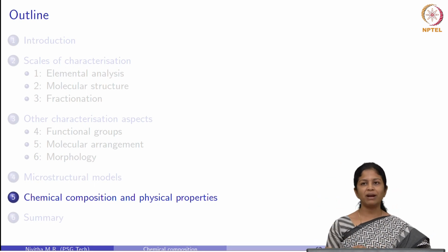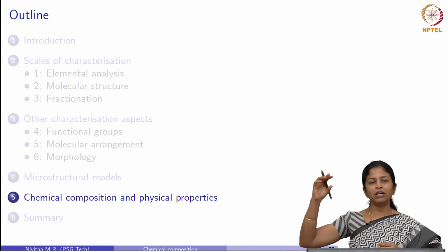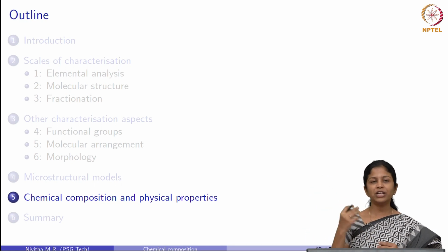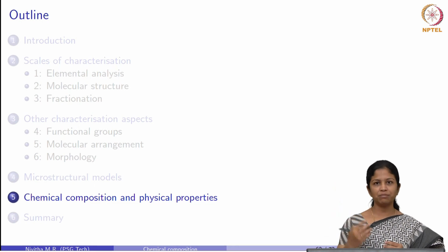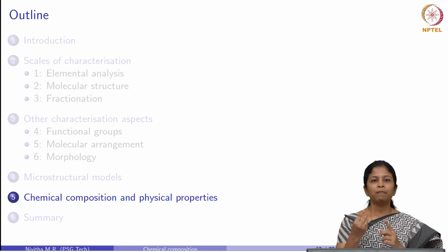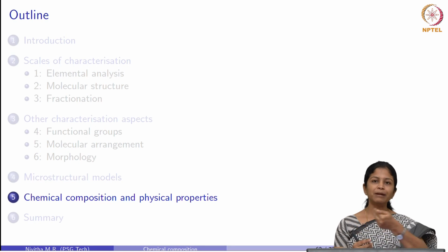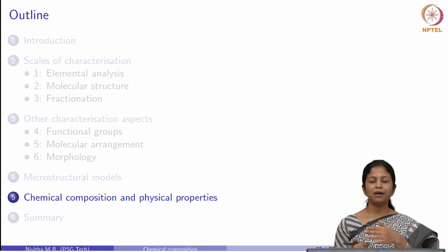So, why do we need to understand this? We have some particular property of bitumen, say for example moisture damage. We need to reduce the moisture damage in bitumen. So, we need to make this bitumen have more affinity towards the aggregates, and when moisture interferes in this system, it should not rip away the bitumen from the aggregates very easily. For that purpose we need to ensure a strong bonding between bitumen and the aggregates.